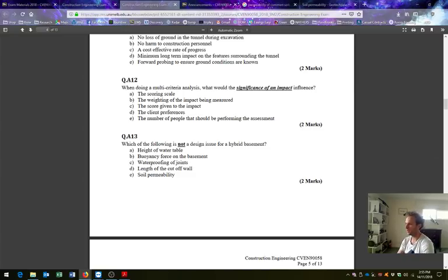Check that for me. So 2016 exam A16, the option D stated diaphragm wall cannot form an effective water seal due to panel joints. Can we take this as true? No, it's not true though, because we will put in hydrotite between the panel joints, and that would make it form an effective watertight seal. So hopefully that answers the question.